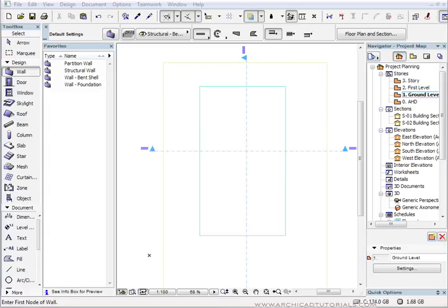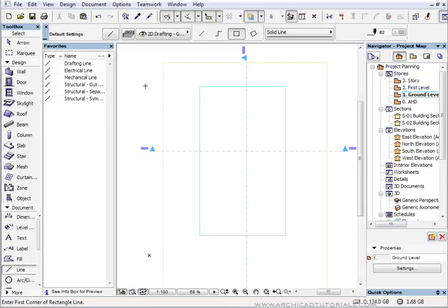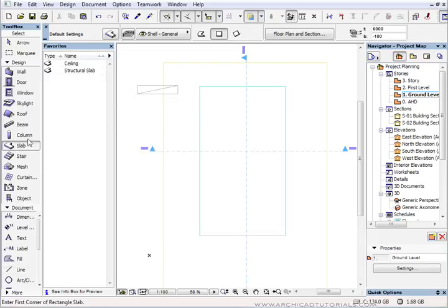Now the third thing when you're modeling something, let's just say a light fitting: if in 2D what you used to do is just draw a rectangle like that with a line through it like that, let's make sure that when you model it in ArchiCAD you just create a square with a line through it. So if you were going to model this light fitting in ArchiCAD, maybe you just grab it and draw a slab, put it at the right height, and then maybe put a line through it as well.